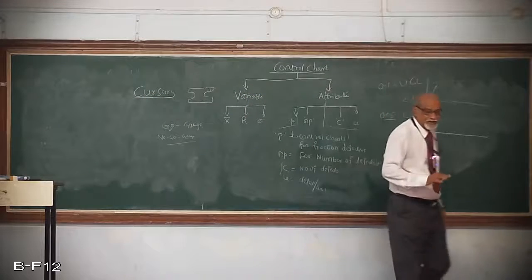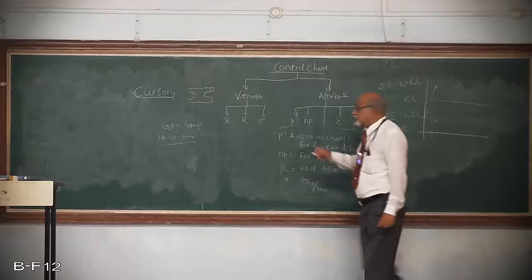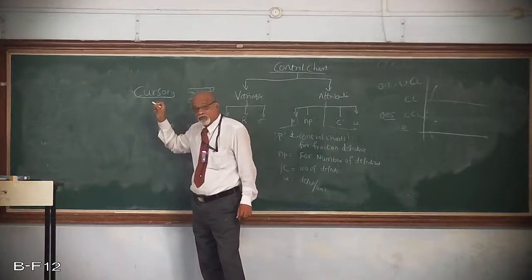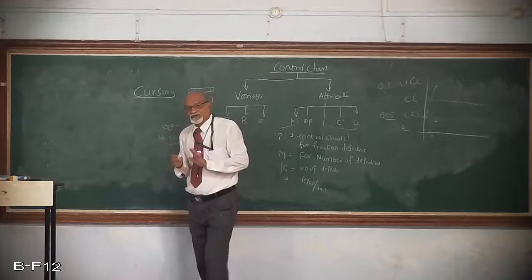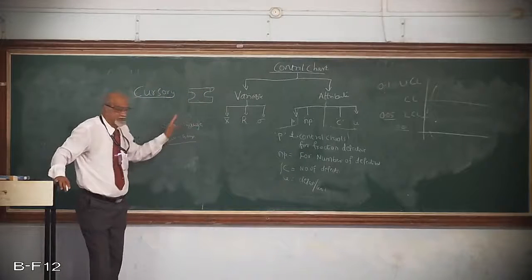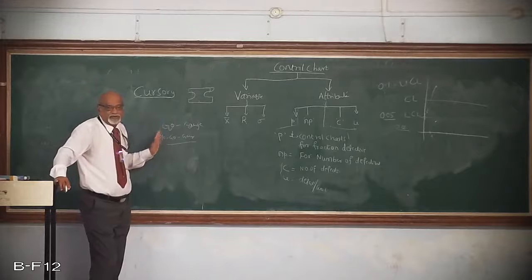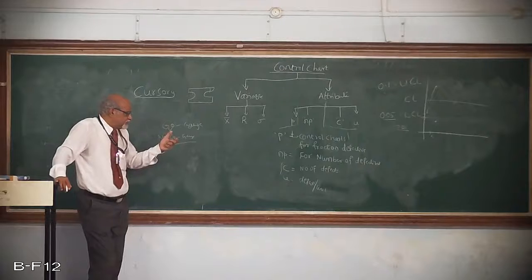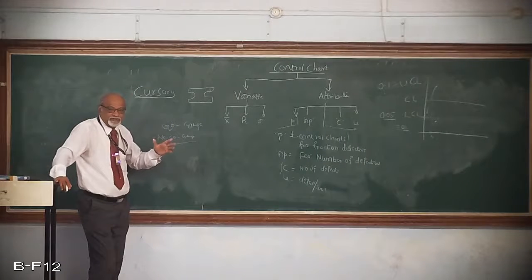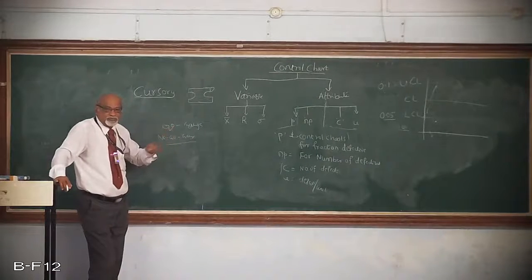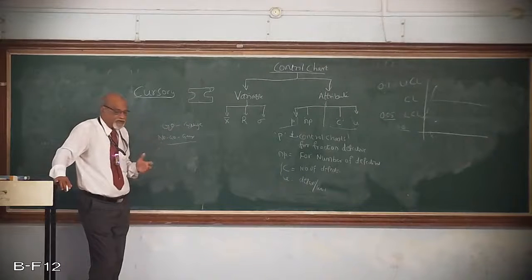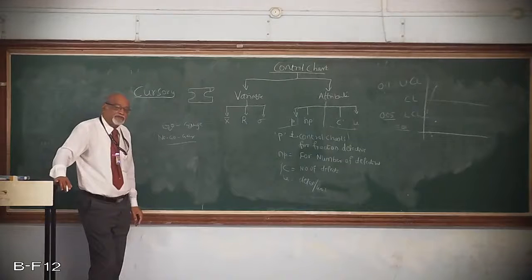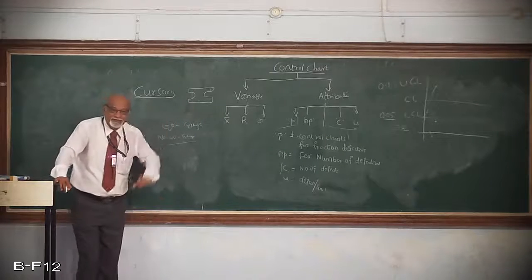Right? Okay, of course, I'm talking about that. So what is the actual measurement? Whether it was 20.1, 20.01 or whatever, no. It will tell whether it lies between the upper specification limit and lower specification limit or not. That is what we want. So it will be very fast, because instead of measuring one accurate dimension, I can classify the articles into defective or non-defective by using go gauge and no go gauge. So even if it is a measurable characteristic, we will be using that. That is what I told you.